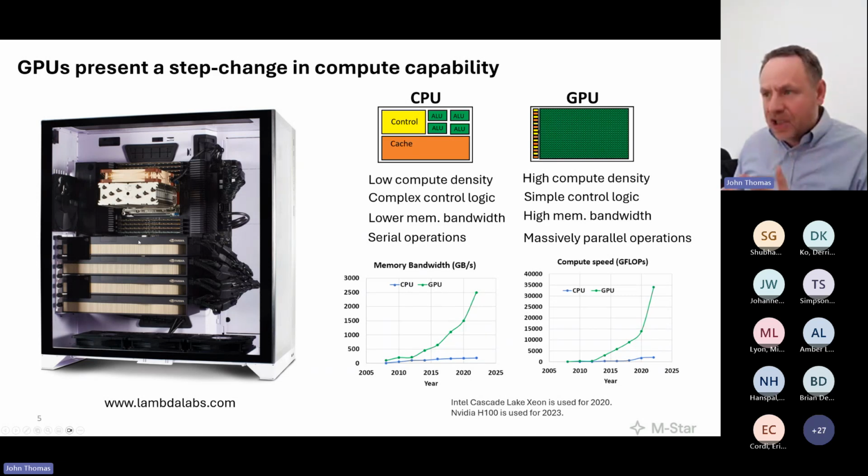So what you're looking at here, this is the GPU. There's the heat sink and cooler. Underneath this thing is the actual logic unit and the memory. But to be sure, all of it's local, which makes memory bandwidth very, very high on a GPU. Further, it's an order of magnitude higher than trying to travel through the PCI bus. Furthermore, the compute density means that a standard GPU can do math an order of magnitude faster than a standard CPU, even with multiple cores.